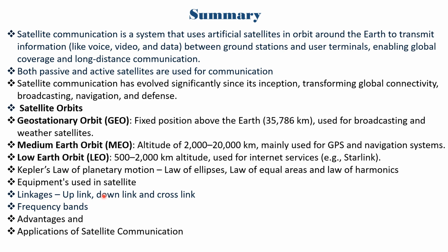All the ground equipment along with the transmission path and receiving antenna at the satellite are included in the uplink system. And coming to the downlink, it is a communication from the satellite towards the earth station, and it is described in terms of satellite transmitter output, downlink antenna gain and beam width, and the ground area that the transmitted signal will serve.